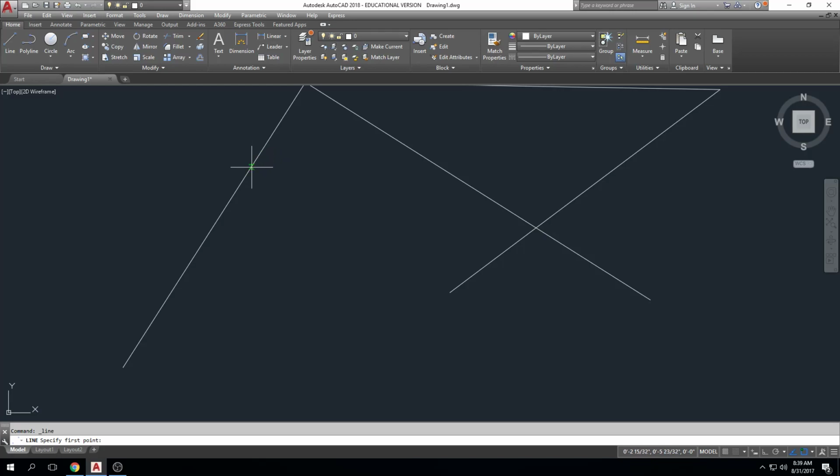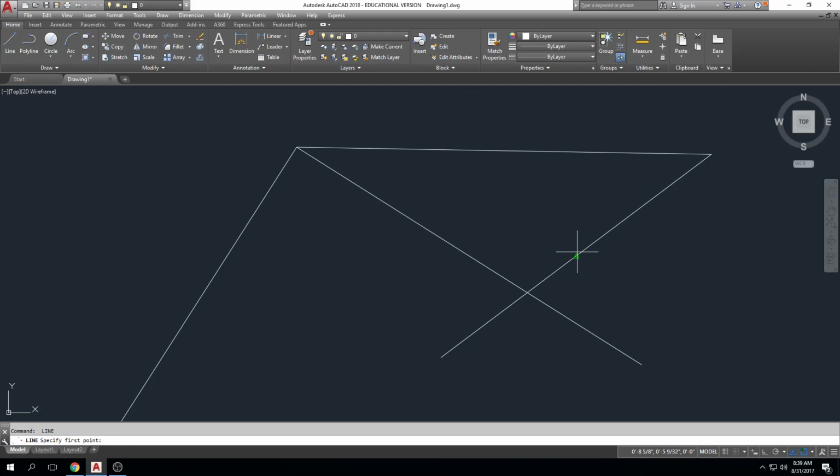Okay, I drag my mouse down this, and as I approach the center, oh, there's the midpoint, that engages, right? I drag my cursor down, there's the endpoint, okay? If I'm drawing a line, click, and I want to get a perpendicular snap. Ooh, let's see if I might not be able to get a perpendicular snap here. Let's do it here. Okay, there's nearest, let's see if I can get... there's my perpendicular, right?